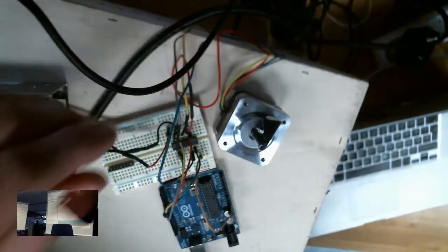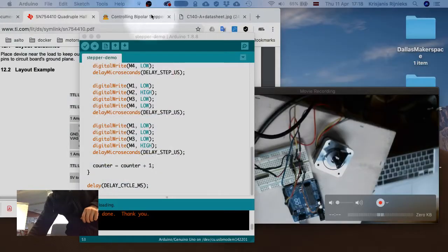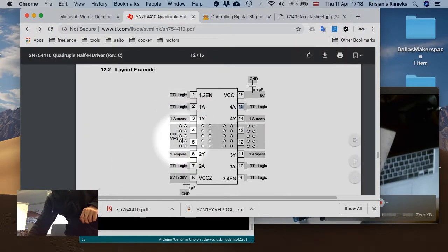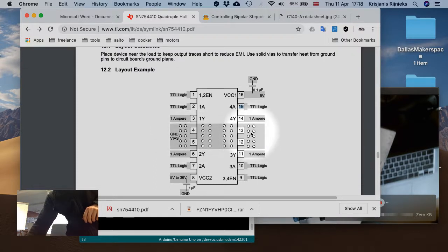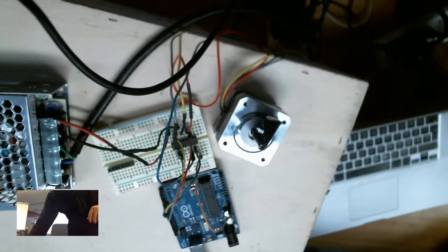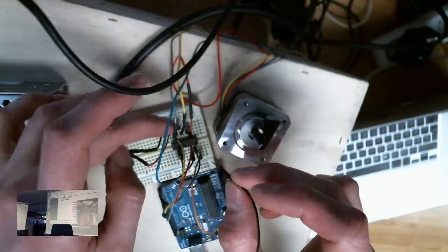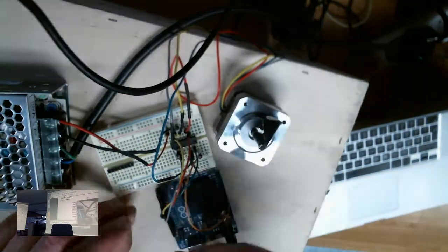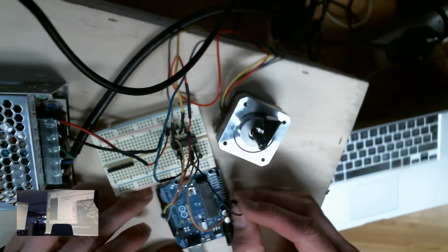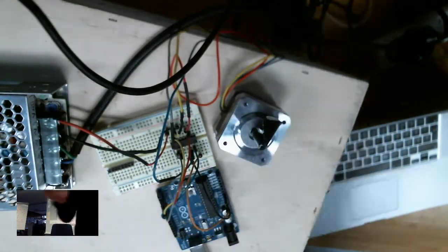of the chip. So if we examine the data sheet again, here we see that these 4 pins in the middle are for the ground, for all the grounds. So these are all connected, and we need to connect the ground from the power supply with the ground of the Arduino over here. So for that, I'm gonna get another black cable. So I just connected the power supply ground, and let's connect the Arduino ground over here, and let's plug it in now.